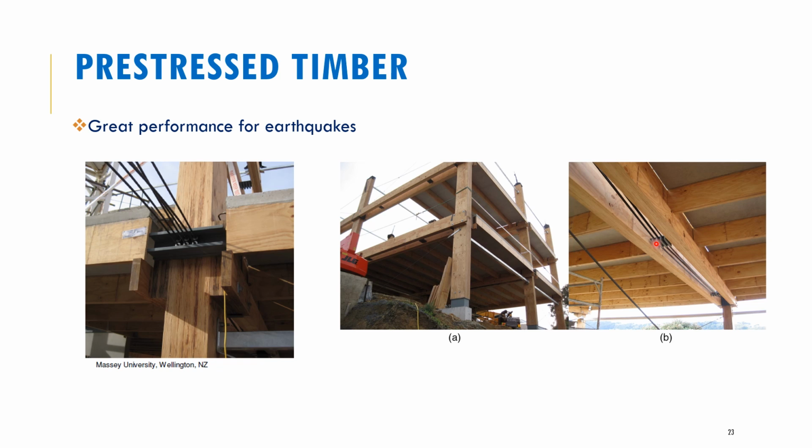bigger than your usual spans, so long as you have these tendons attached that are tensioned to a particular strength specified by a structural engineer. And the use of that is because it gives greater performance when it comes to resisting earthquake loads. So in regions where there's heavy earthquakes, or there's heavy horizontal loads from winds that need to be resisted by the structure, it's best to adopt pre-stressed timber.